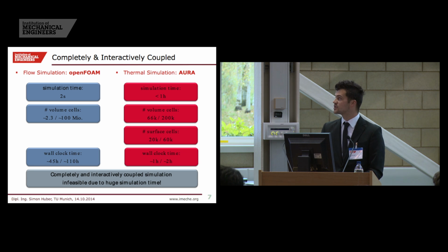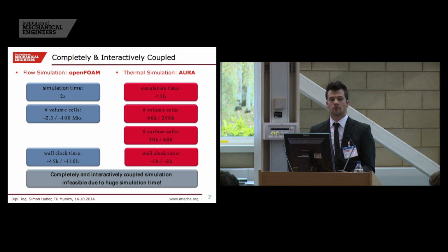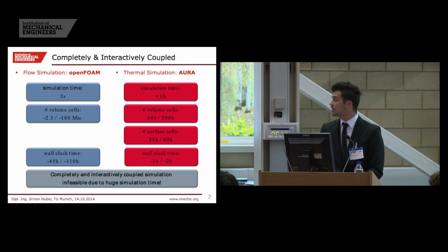For the flow simulation, I have 2.3 million cells for the cube test case and 100 million cells for the car test case. And on the thermal simulation, I have only like 60,000, 200,000 volume cells, and some surface cells for the radiation. But the thermal simulation is done in 1 hour, 2 hours on a personal computer, and the flow simulation takes up to 6 days on the cluster.